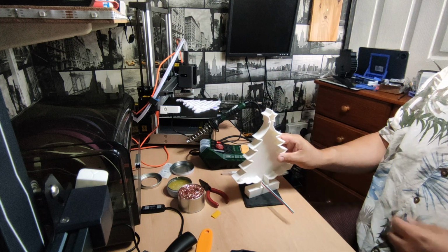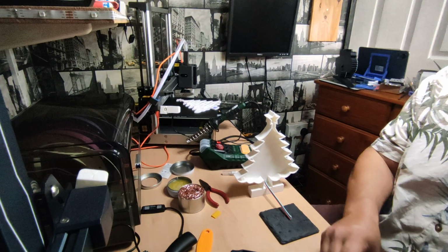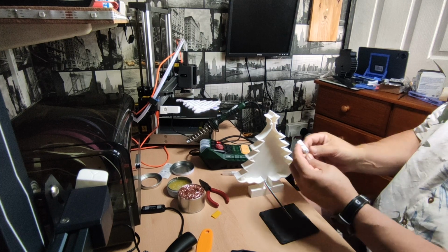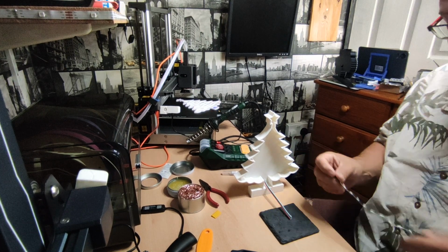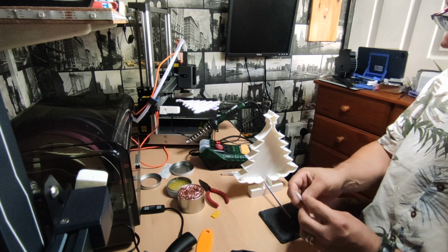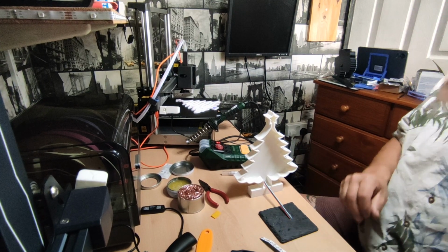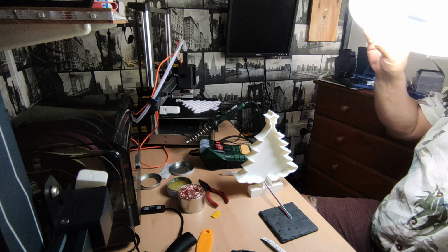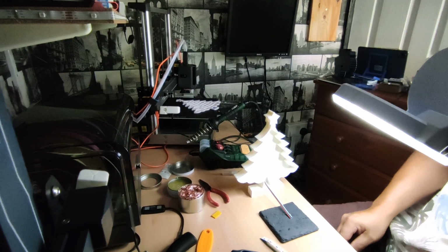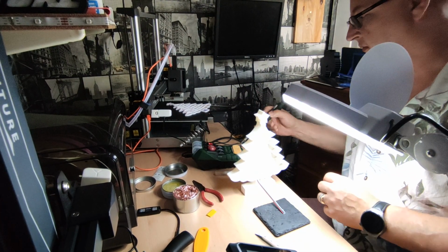So I need to solder the wires onto the LED strip. Positive is the one on your left, which corresponds to my red. So we've got red, green. Green will be a signal wire and ground will be the white wire. Because my eyes are getting a bit dodgy now, I need my little magnifier. Let's move it back slightly so you can see there.